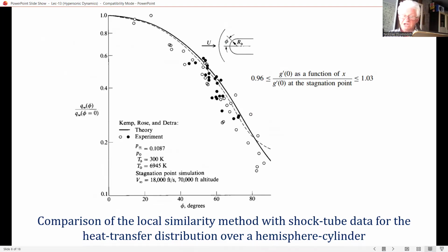This physical defect does not appear to be serious, probably for the following reason. The boundary layer equations are parabolic partial differential equations. For such equations, information is readily transmitted across the flow, normal to the surface. At the same time, information is carried downstream. However, the history of this information dies out quickly with distance downstream.